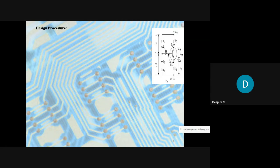Usually the capacitors we are having, we remove those capacitors and retain only the resistor combination. For analyzing purposes, all the DC components, that is the capacitors, are open circuited. Therefore we are going to select VCC, the collector voltage, as 10 volts.